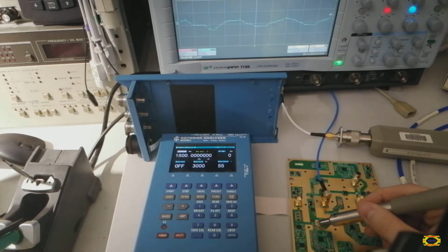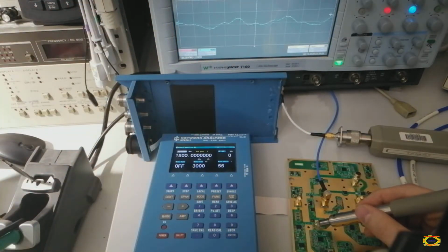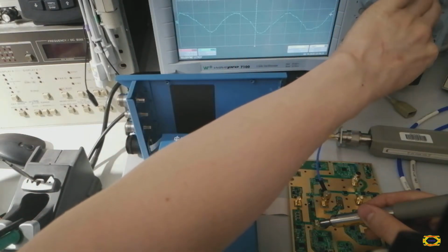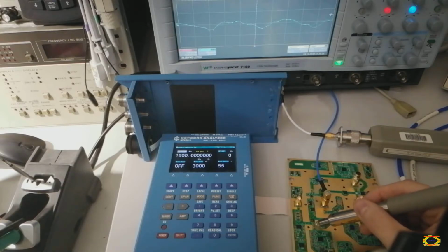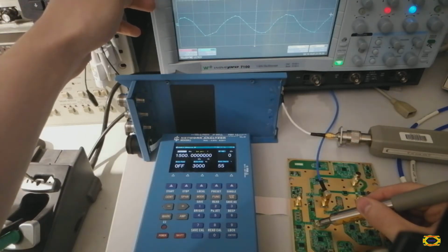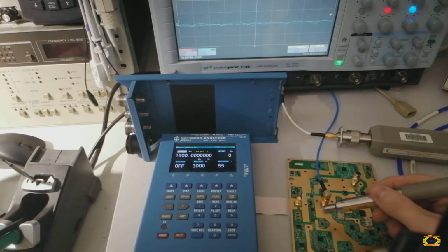And yeah, we definitely can see something. From this synthesizer we can see much higher amplitude, even directly from port 2, but we know there is some amplification. So even at the input of the RF switch we can see, sorry, I really have to adjust it again. We can see around 200 millivolt peak to peak amplitude. Yeah, roughly so. But at the port 2 we can see just 10 millivolt. It's ridiculously low. So okay, let me find the next component.